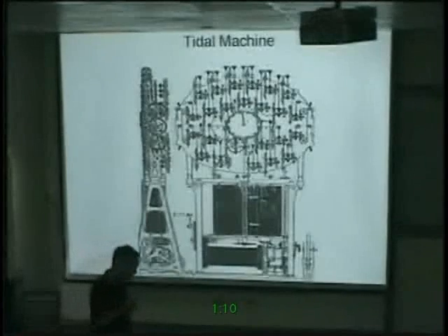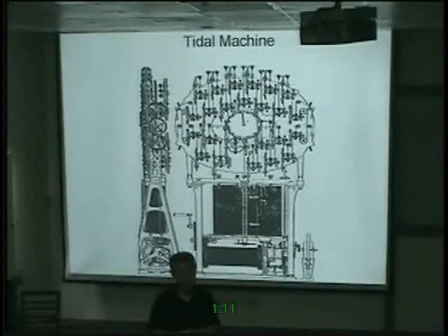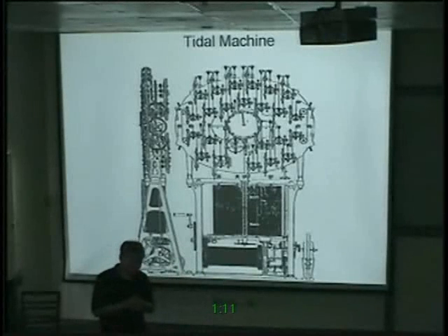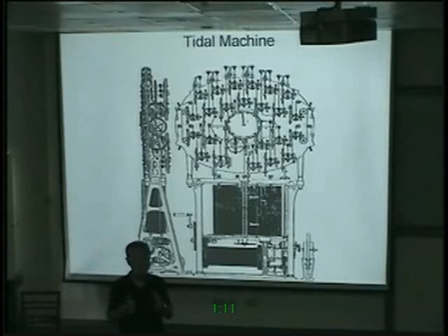Reason number one, even though tide is Laplace tide, you can solve the Laplace equation for tide, but the boundary condition is never linear. Second, tidal wave propagates in shallow water, and the shallow water equation is never linear. And third, when we measure tide, we never measure in the deep ocean. We measure in the coastal region. All the tidal stations are near harbor, at the entrance of harbor. And that deep water wave coming to the tidal station, that transformation is not linear.